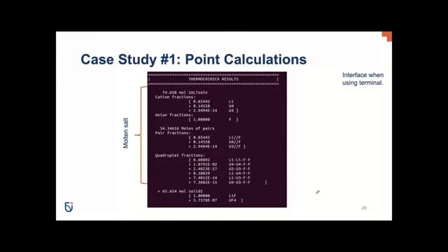But so in this case, the user can say, hey, I've got this much lithium fluoride, this much uranium, and this much fluorine at this temperature and pressure. And in this case, we're using the JRC database. And then Thermochemica will return this as output and say, okay, we're going to be predicting that we have 74.65 moles of your salt solution and 65.65 moles of some solid solution under this particular example.